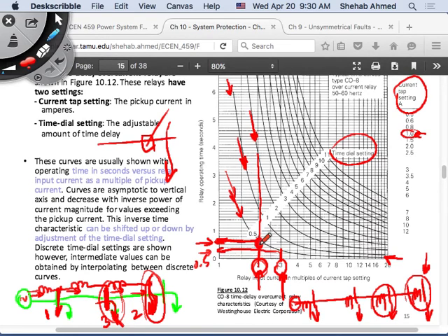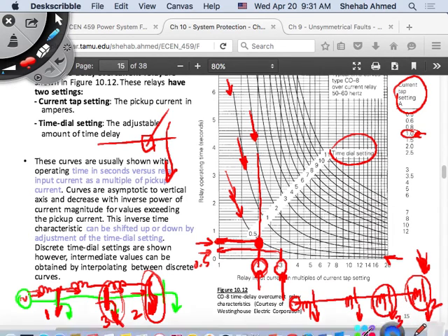No? Yes? If two relays are after each other, right? There's one here, and there's one here. The fault is happening on this bus. For a fault current on this bus, the fault current is 2 amps, for example, because remember, this is the larger impedance. If the fault happens on this bus, the fault current is 3 amps. Okay?